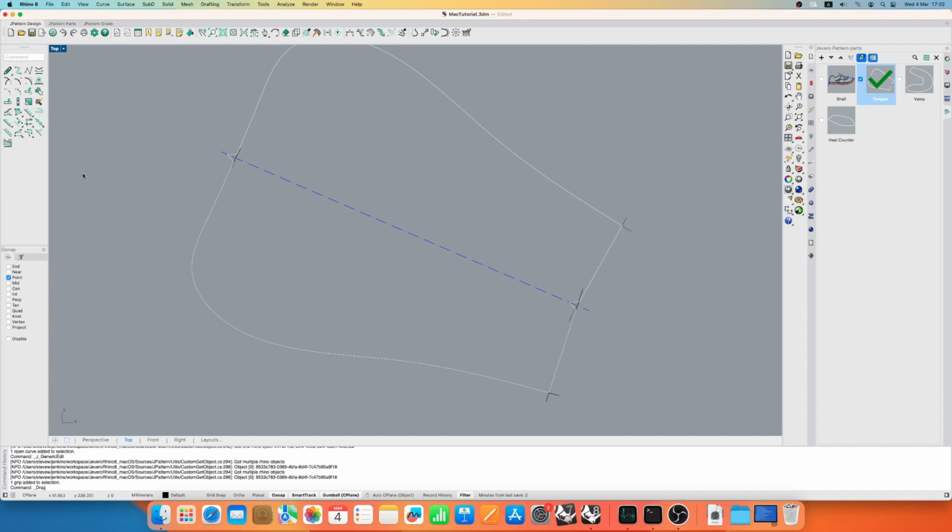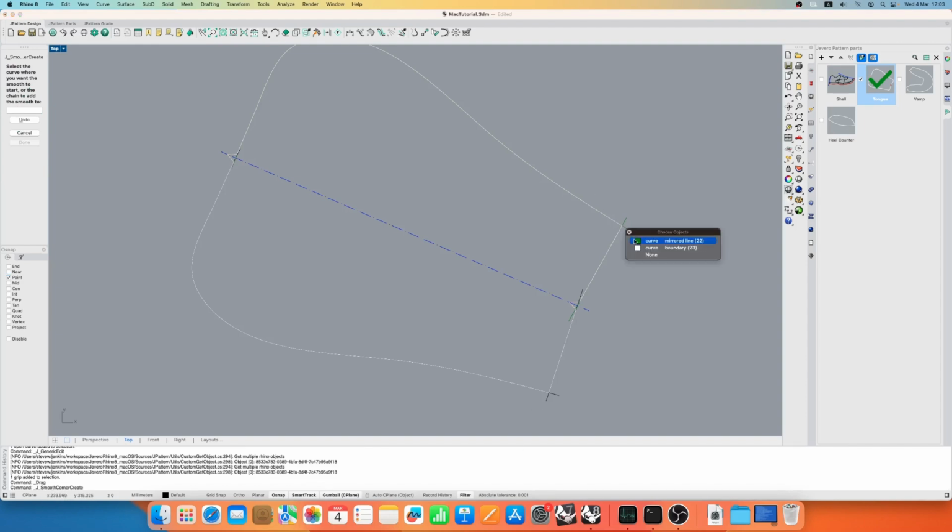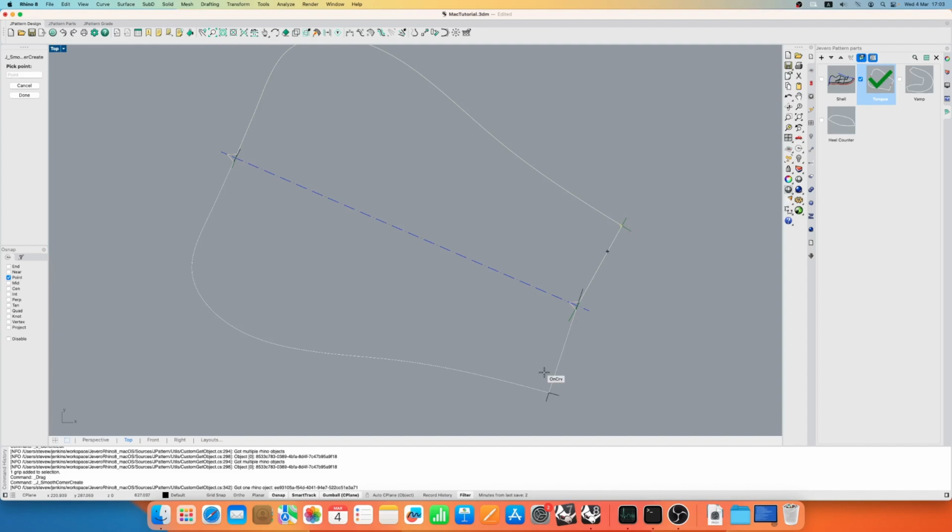The next thing I want to show you, as I mentioned, is the rounding of these corners here. So I'm going to pick my boundary, add a rounding here and a rounding here. And then I can choose how much and how big the rounding should be. So let's make it very thick, like 5 millimeter. Here I have it very rounded around here.